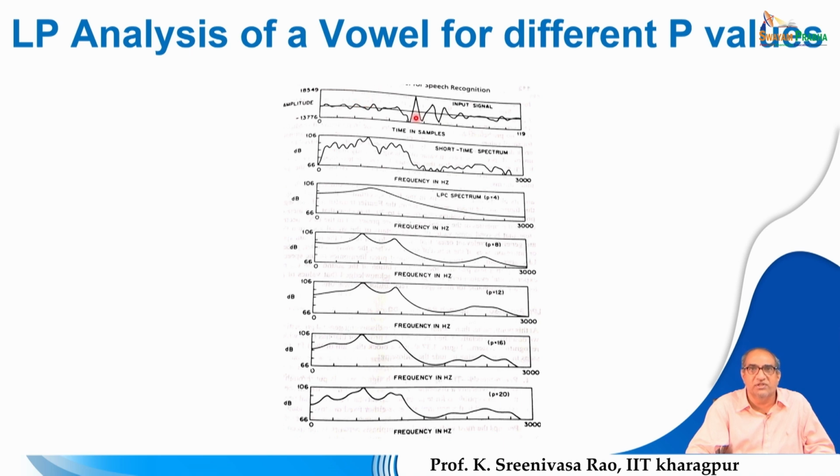That is the reason that here, when you are analyzing the spectral envelope captured by the linear prediction analysis, for the analysis purpose we considered the vowel segment, and we took around 20 milliseconds of the vowel segment. It means around 120 samples were considered, 0 to 119, so for this particular vowel segment, if you compute the spectrum using the normal fast Fourier transform, you can see the spectrum will be this one, and this spectrum corresponds to this particular speech signal.